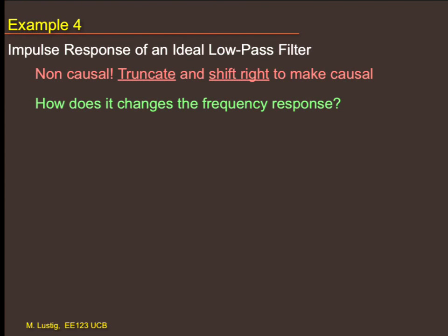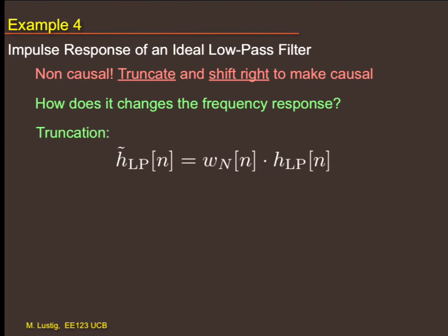What is truncation? You chop off. Can you write it as a function, mathematically? Yeah, you can write it as a mathematical function, but you have to limit it. So you say from time... how do you limit something? Multiply by a window function. What kind of window? A rectangular window in this case, because you just crop it. So you multiply by this rectangular window.